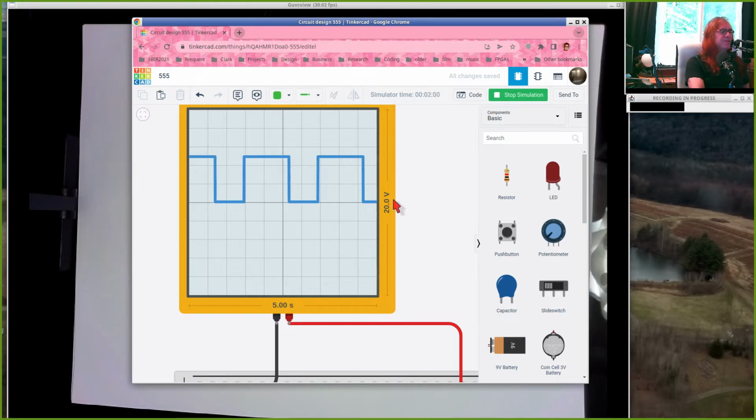And then 20 volts going from the top to the bottom, and there's 10 divisions from top to bottom, so each of these lines is 2 volts. So there's 2, there's 4, up here is halfway through the next division, that's 5 volts. So now I can screenshot this, and I can draw that, and say this was the observed waveform.